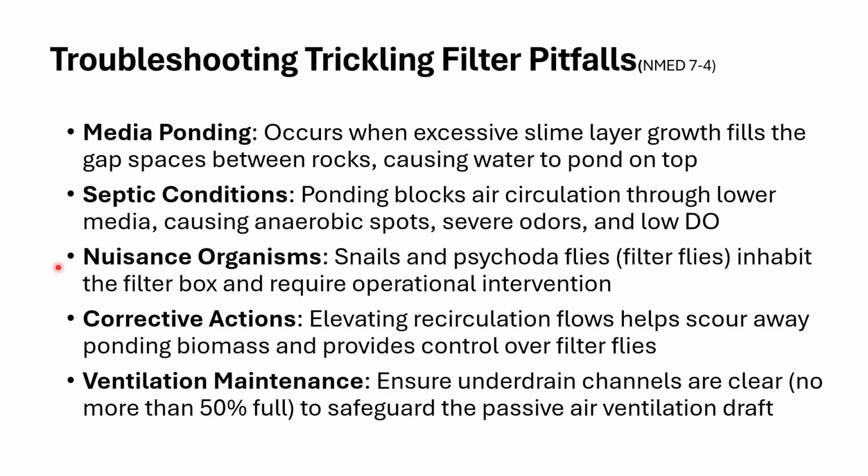Okay. In addition, we can have nuisance organisms build up. Snails and what are called Psychoda flies or filter flies, they'll get inside the filter box, and then you're basically going to have to go in there and you're going to have to clean things out to get rid of them. That's what operational intervention is. You're going to have to clean stuff out and you're going to have a mess on your hands.